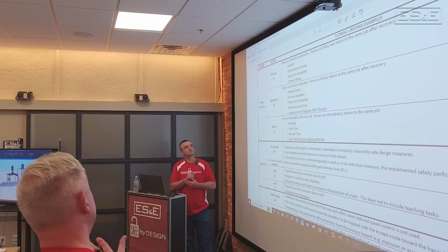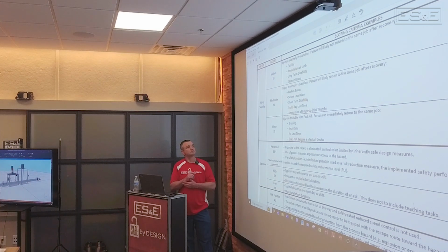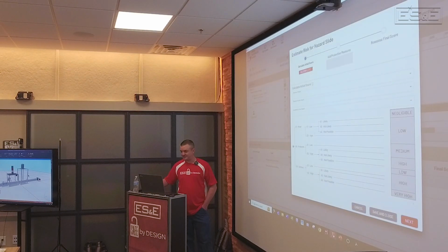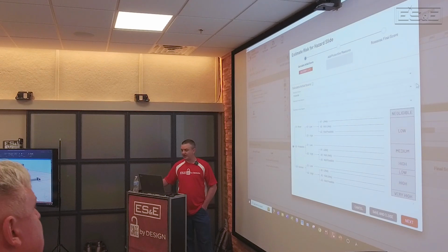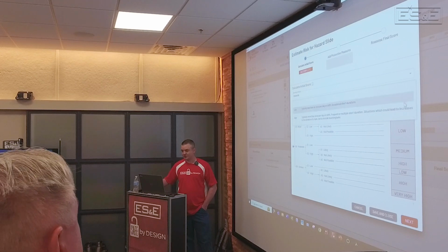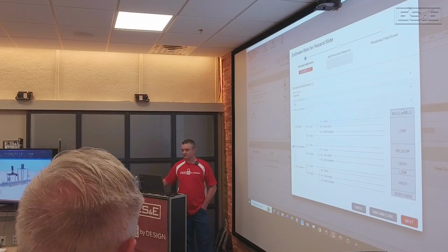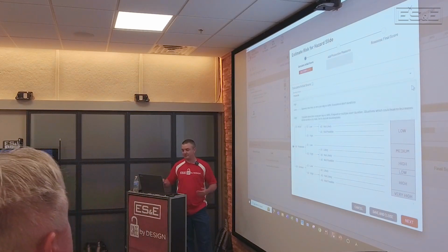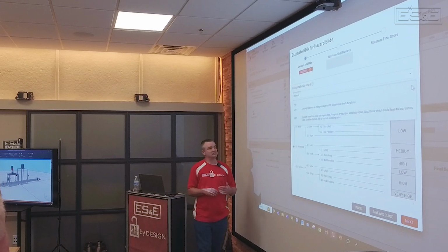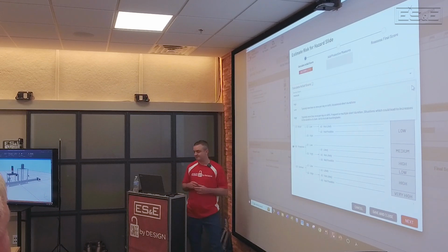So broken bone, definitely. Severe laceration, maybe. Yeah, so moderate, S2. It looks like moderate would be the thing that we would do there. I would agree with that. So again, we'll rank it as a moderate. Our exposure to the hazard: oh, it's going to be every cycle. So our exposure would be high. Yeah, for sure. Again, because that's based on the definition. More than once per day or shift, it's pretty much high. Yep. Okay. Got it.